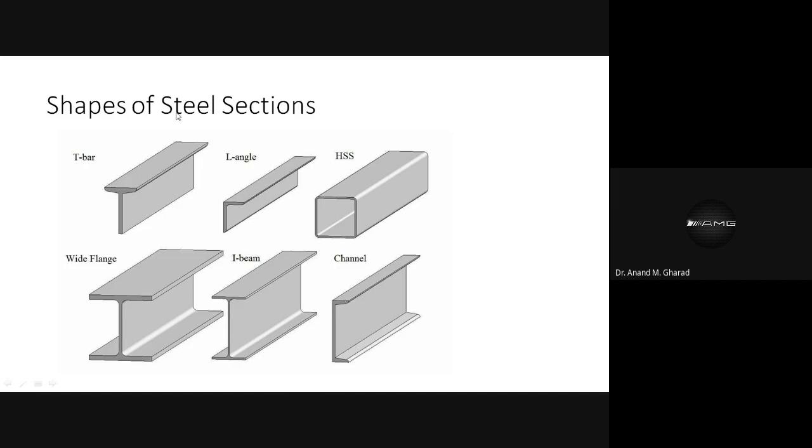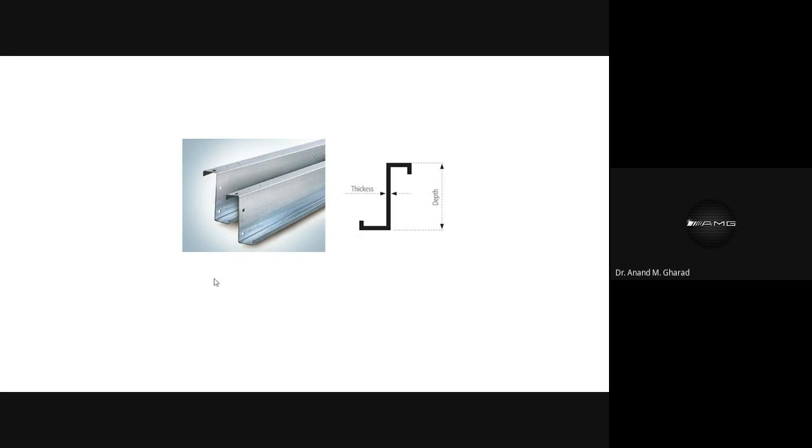These are the different shapes of steel which we will be dealing with. Frequently you will find I section, channel section and angle section. Okay? These will be used. This you can call the output result of cold rolled section. Okay? These are typical shapes and they are not used in the main members like the column and beam. They can be used in case of purlins.